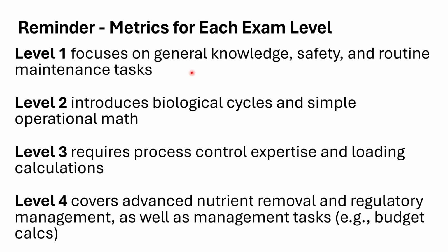I want to remind you what we're looking at on these different levels of exams. For level 1, the material is going to focus on general knowledge, on safety, and on routine maintenance tasks. Okay. Think about where a level 1 person is in a municipal wastewater plant. They're doing sampling, they're raking off the bar screen, taking a sample of sludge in the primary clarifier with the sludge judge.